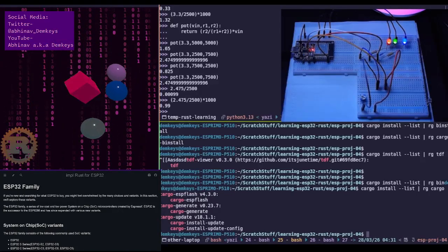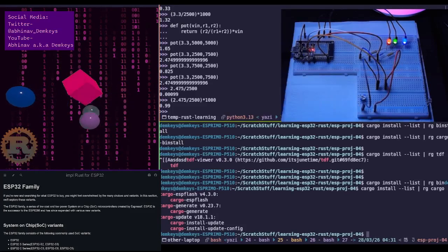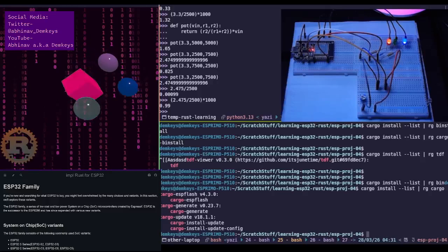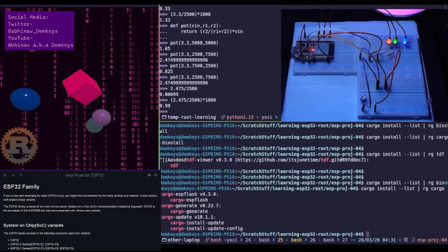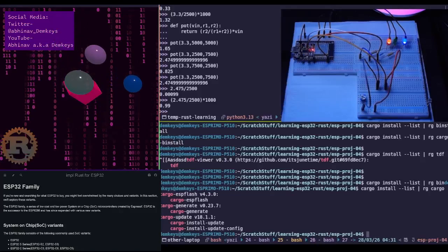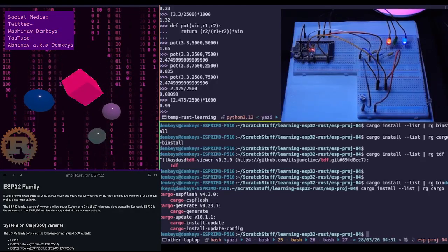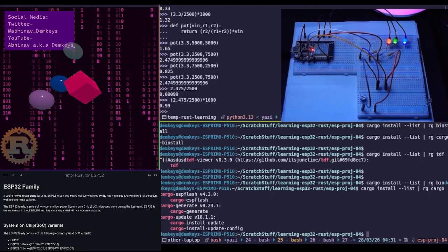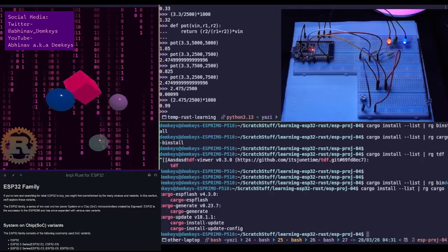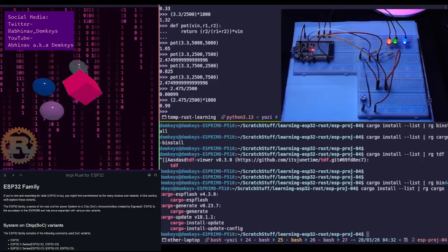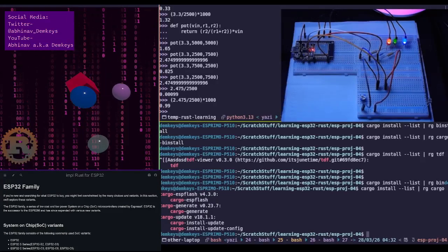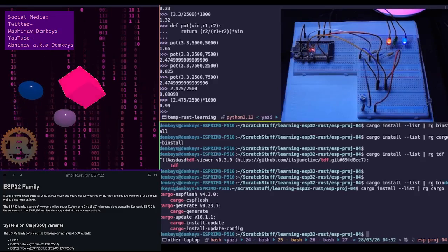You can give it a pulse to get sound from it, and this is like output from the microcontroller. At the same time, if you give it mechanical force, you can actually generate a pulse and send that back to the microcontroller. So that's something you need to be careful of when you're connecting the thing directly to your microcontroller. And at some point, I would like to explore that. But yeah, we have piezoelectric.